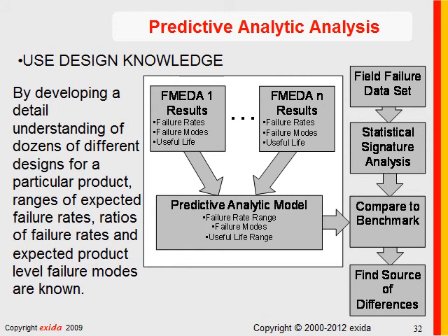Earlier I talked about the concept of predictive analytics. The concept is use all the information available to generate the best failure rate data available. What information is available? Design details. An FMEDA analysis shows the design details. We know exactly what components are used. We know exactly what design margins are being used. We've done fault injection testing to show what diagnostics are present.